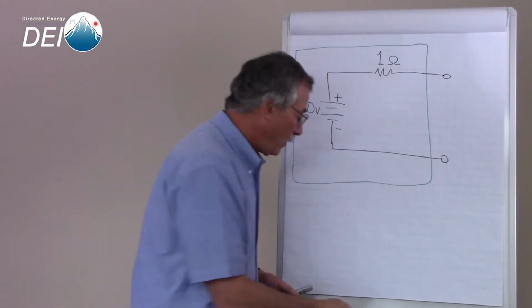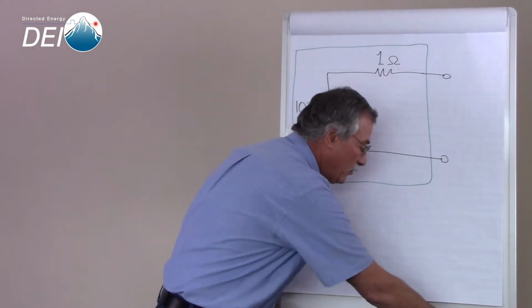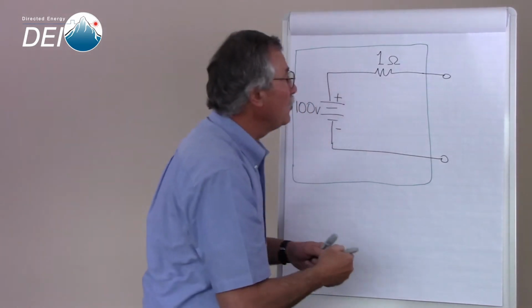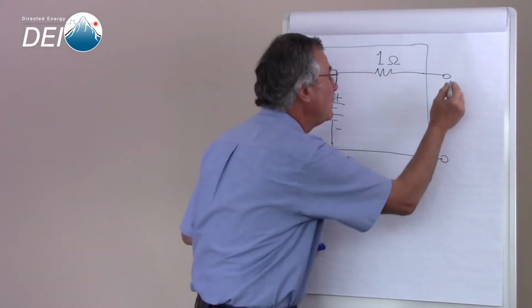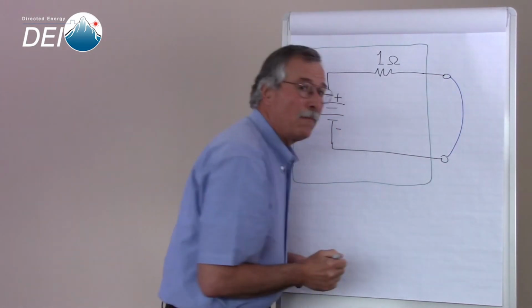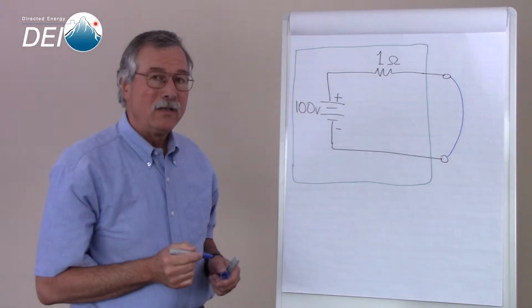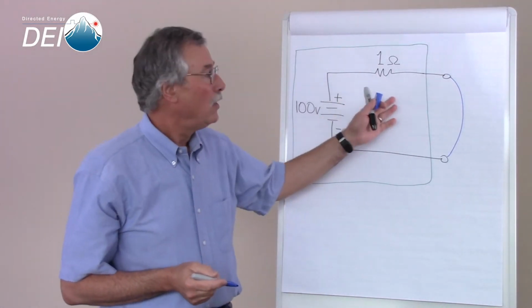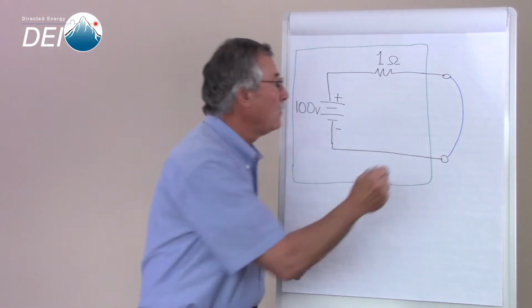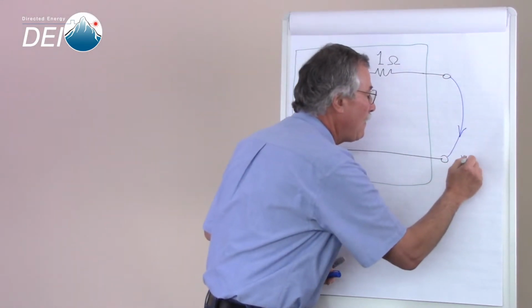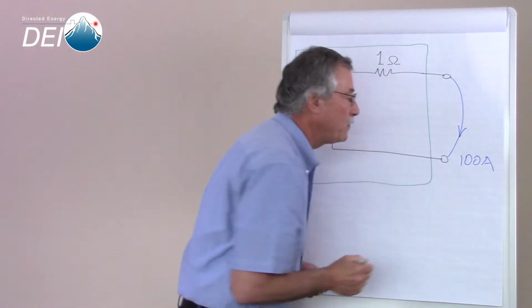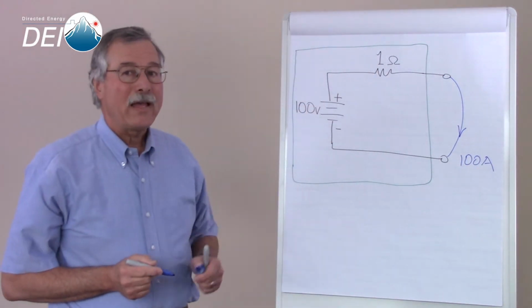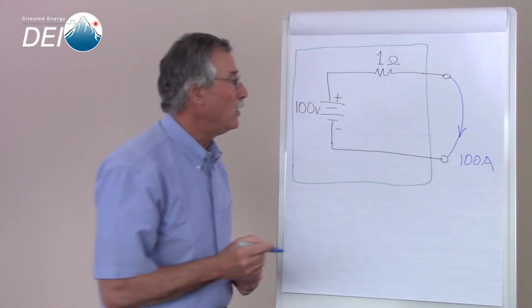How does it work? Well, let's try, first of all, using a short circuit as our load. What's the current flowing in our load? Ohm's law tells us it's 100 volts divided by 1 ohm, or 100 amps. Now let's say I add a little bit of resistance to our load.